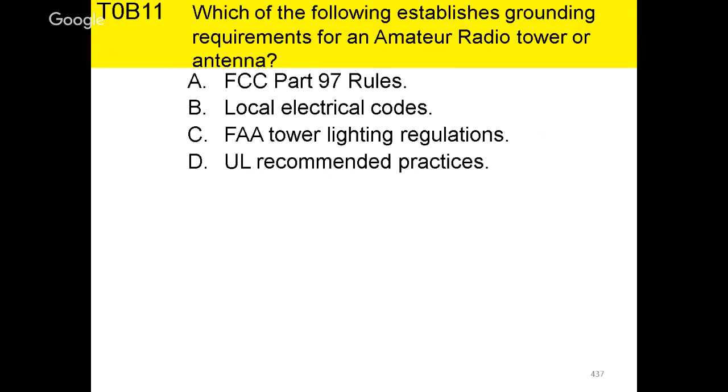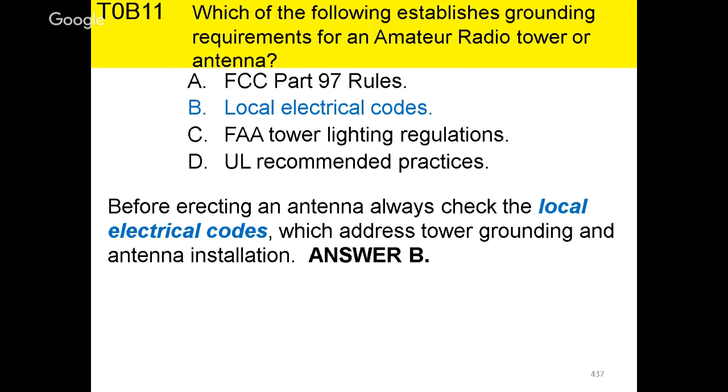So you really want to follow the local electrical codes. So before erecting an antenna, always check those electrical codes which address tower grounding and antenna installation.